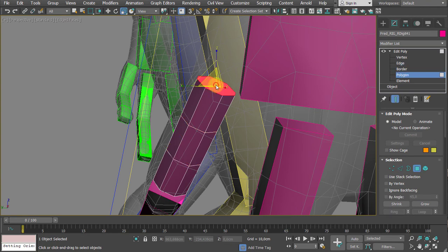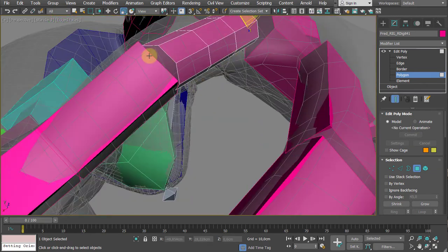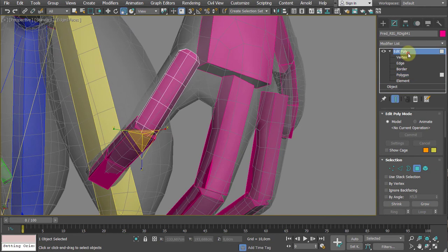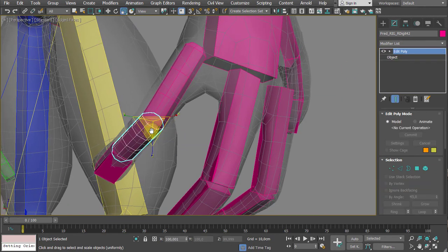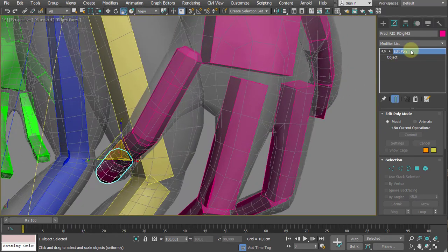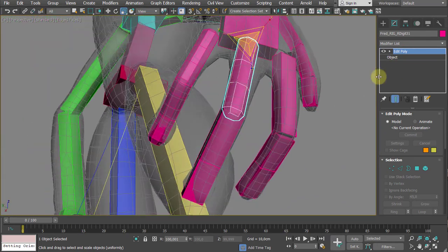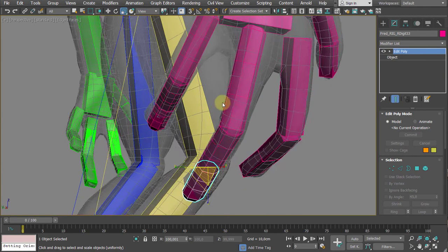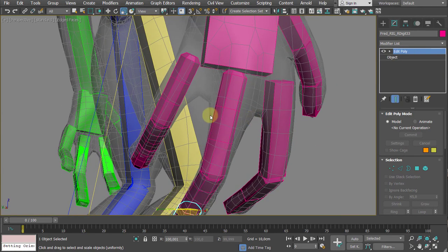So number 4, Shift E, tiny extrusion, R, and pulling it back, and Shift E, and pulling it back. Okay, so here it is, this is the base, and then I can copy this base all around. So drag and drop everywhere. Okay, so of course then you have to walk through and convert everything.